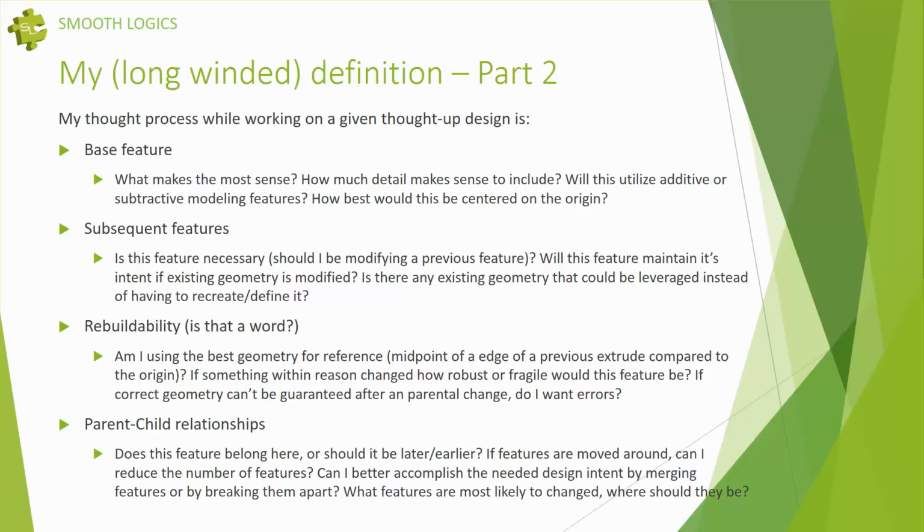questions. In Darren's sketching class, he talked about he doesn't like sketch fillets, and I agree with him. I like feature fillets. The number one reason I dislike sketch fillets, they have their place, and I do use them. But the number one reason I like feature fillets is because you can have a single feature of a single radius filleting various geometry throughout your model. You're not constrained to a single 2D sketch plane.